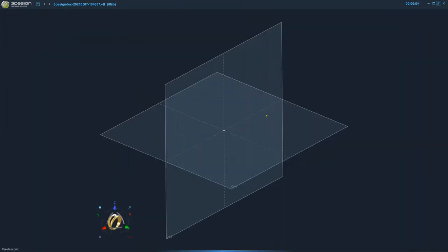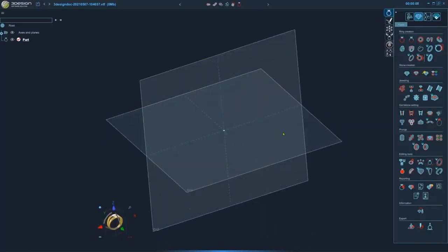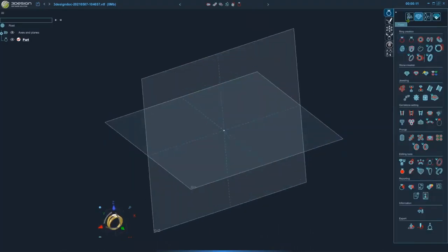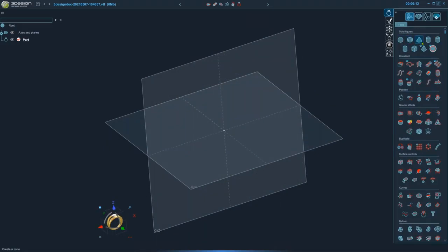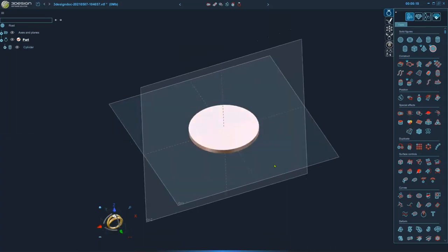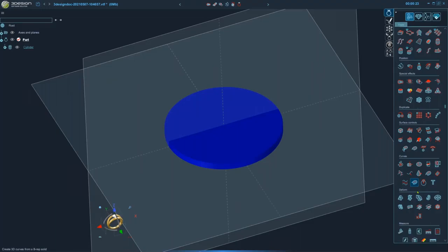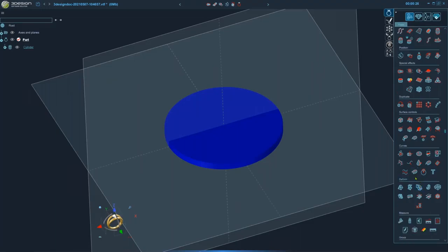Okay, next up we have a couple of border tools for doing mill grain or rope type borders. So I'm going to just give a simple example of that. These work with a curve, and that curve can be extracted, it can be projected, it can be a magnet curve, however you get your curves on there, just like if you were doing mill grain any other time.